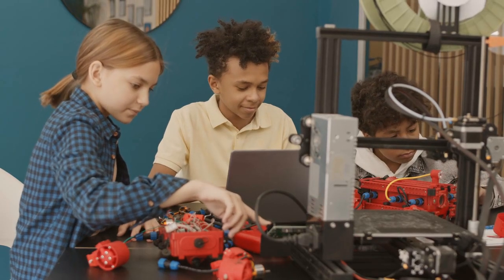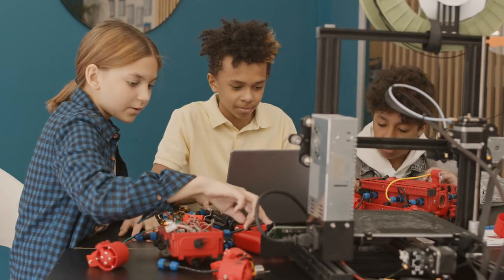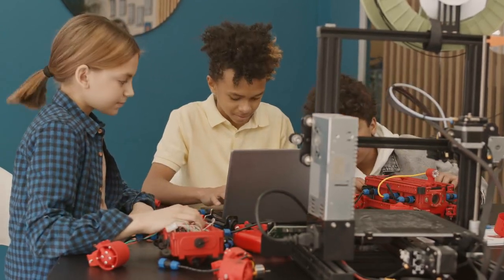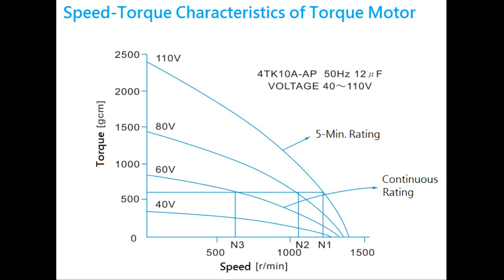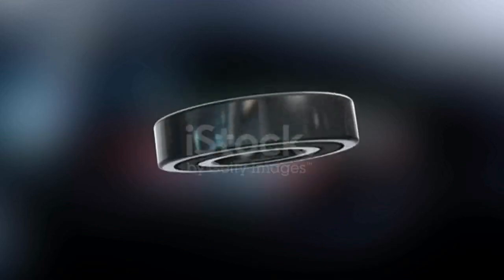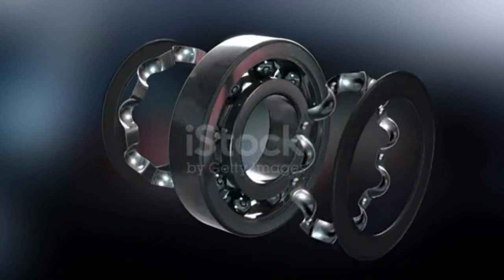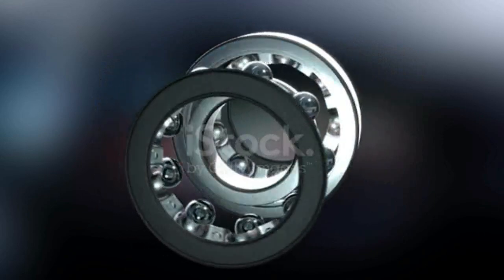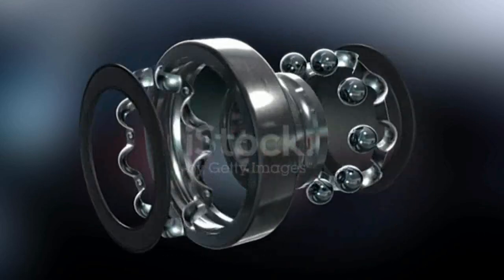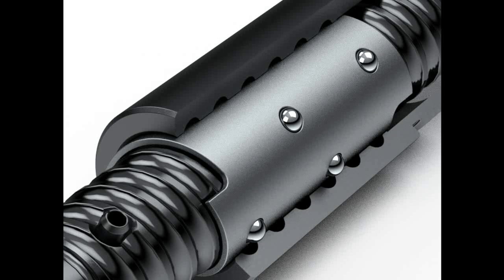Design engineer must know which machine component with what configuration is to be used in the machine. For example, what will be the working torque and peak torque of the motor, according to the working load and starting load in the machine. The bearings must be selected according to the type of loads, speed at which they run and the life for which they are expected to run satisfactorily. Which configuration of LM rails and ball screws are used for translatory motion of machine parts according to the position and weight.